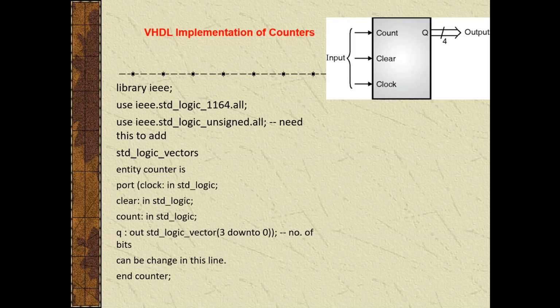So let's define the library first. Library IEEE, use IEEE.std_logic_1164.all. Then use IEEE.std_logic_unsigned.all. Then std_logic_vector, because the counter operation should be performed on std_logic, so std_logic_vector will be used. So let's begin constructing the entity.